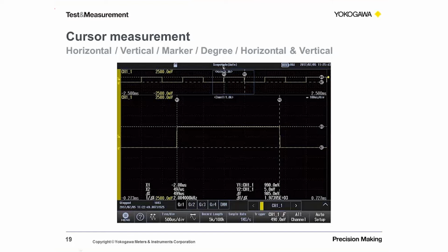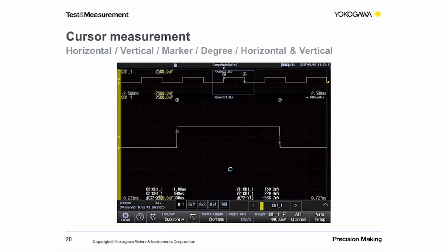So these are, if you like, standard oscilloscope type cursor measurements. We've also then got, interestingly, markers which follow the waveform. So rather than position these completely by hand, you would select which waveform to sit these markers on. In this case, we have one waveform with two markers sitting on the same waveform. We then basically move these and they follow the waveforms you've chosen.